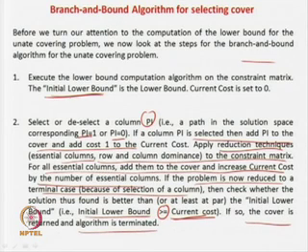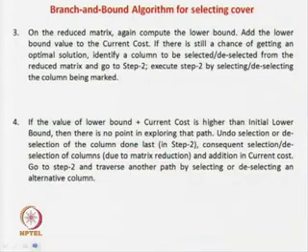Because I told you this heuristic will never report anything on the plus side, it will always report on the negative side. So, for example, it says that 3 prime implicants are required to cover it and your current solution cost is 3, then obviously you have reached your solution, because you can never get anything less than 3. But in the practical case it may happen that you may require 4, 5 or 6. Okay, so if your algorithm is saying that the prime implicants you have covered till now is equal to or less than the initial bound,